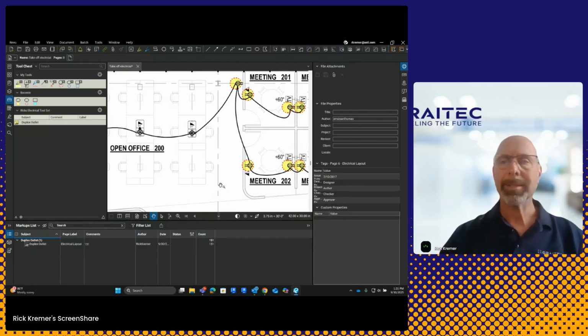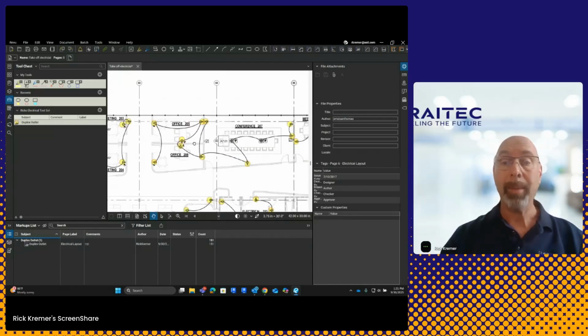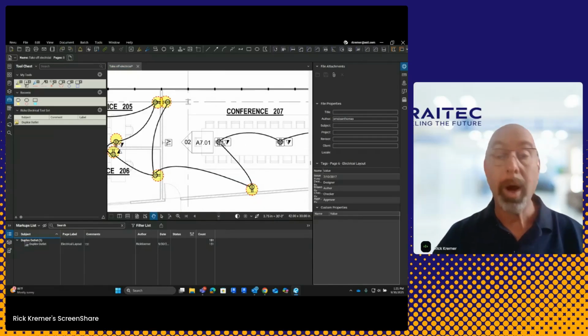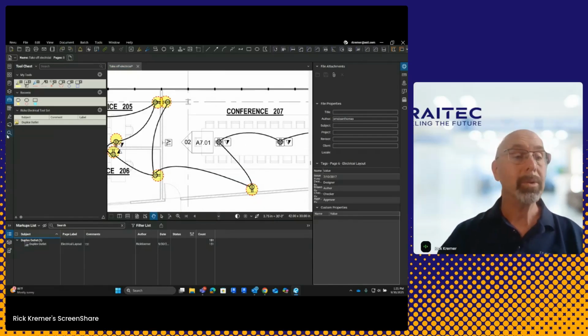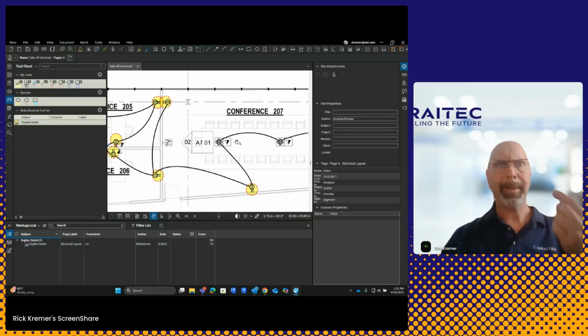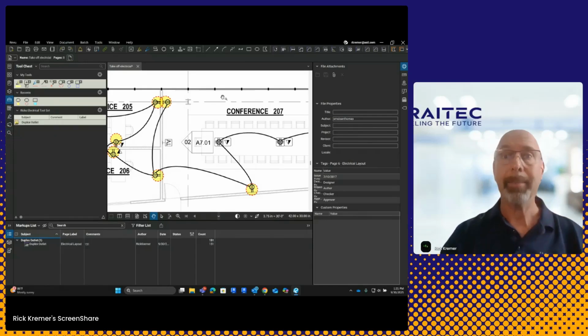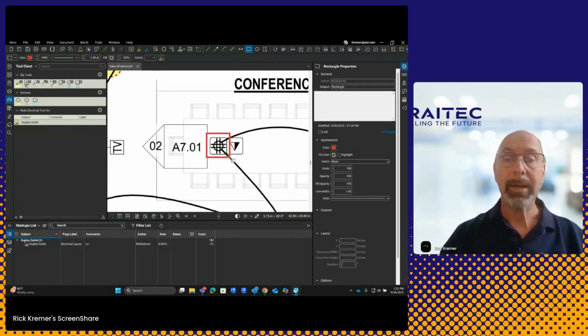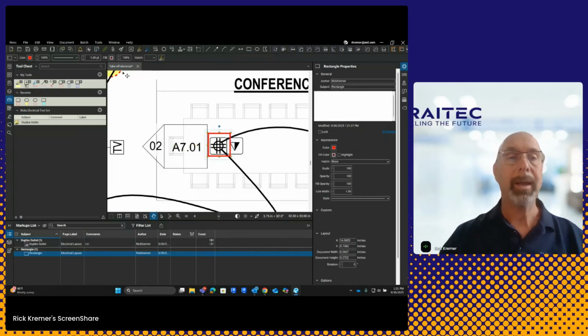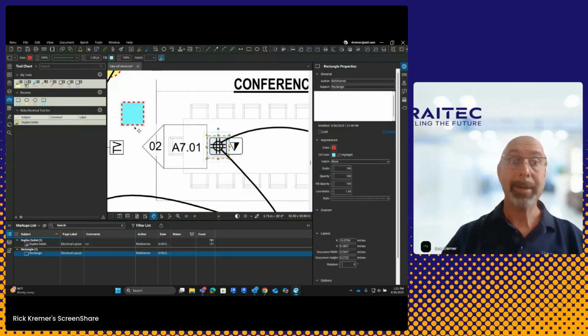Let's count something else. In this case, I'm going to count, I don't know, this quad. Just like before, this time I'm going to create the icon for the quad ahead of time. I'm going to go to a box, a rectangle, and simply draw a box around this. And this one, I'm going to make blue. Let's change the fill to blue and make it hatch. And just like before, I'm going to change the outline over here to dashed. Awesome. So this is the object that I want.